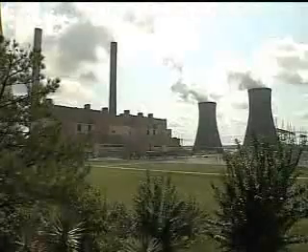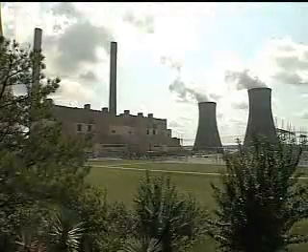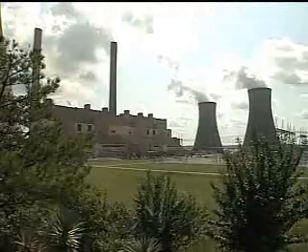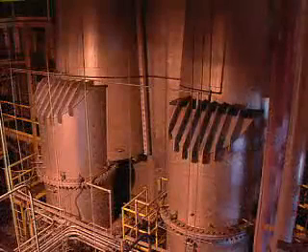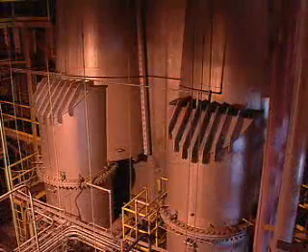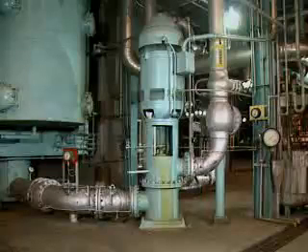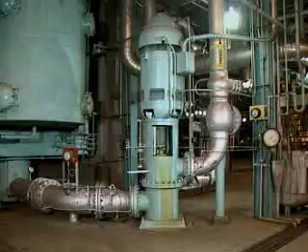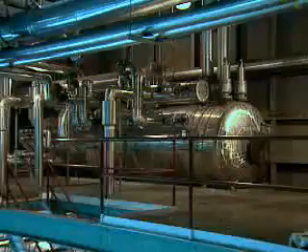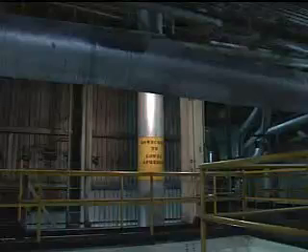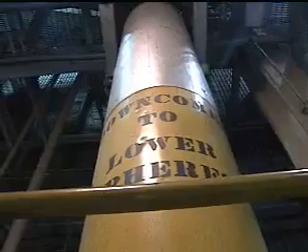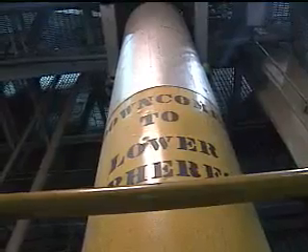In a power plant, the condenser and the circulating water system play a vital role in plant operation and efficiency. Together, these components complete the steam-water cycle by condensing the steam that's exhausted from the low-pressure turbine. The resulting condensate then travels through pumps, heaters, and other equipment in the condensate and feedwater system, until eventually the water returns to the boiler, where it's converted back to steam so that the cycle can continue.